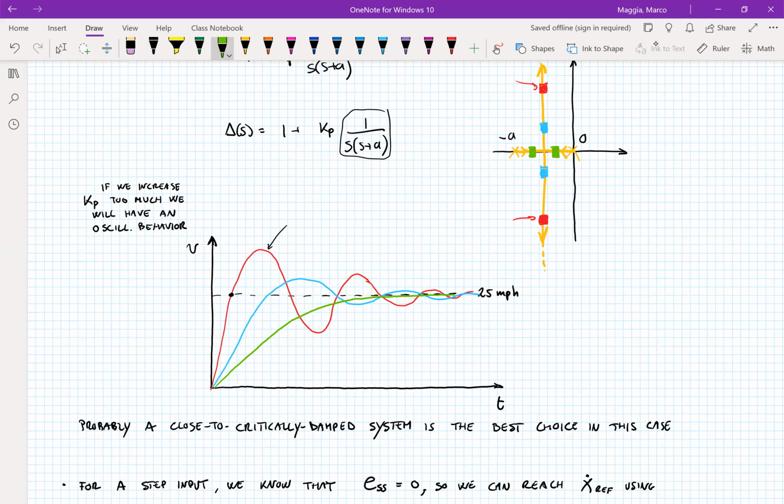And so here we're dealing with a low Kp coefficient. So in this application, you might want to have a low Kp rather than a high Kp. So that's exactly what you want. If you don't want to get a ticket for speeding, you definitely want to have a Kp such that your closed loop poles are real and not complex conjugate.